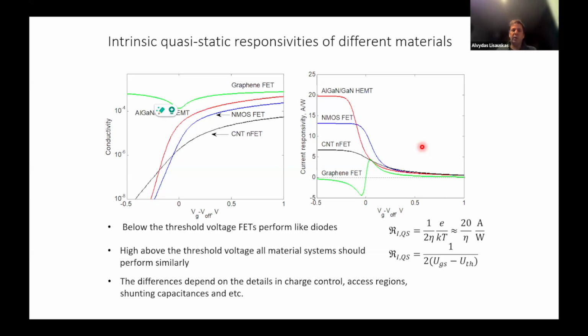What is the diffusion? What is energy transport there? So if one would include the energy transport, diffusion terms, one would find that there is a slight variation there, and even graphene FETs actually, although not being the best here, that's just a realistic curve. I showed realistic conductivity here, which is actually limited a lot by parasitic access regions. Now they are improved. So if I would put some most recent data here, then it would really fit very close to each other.